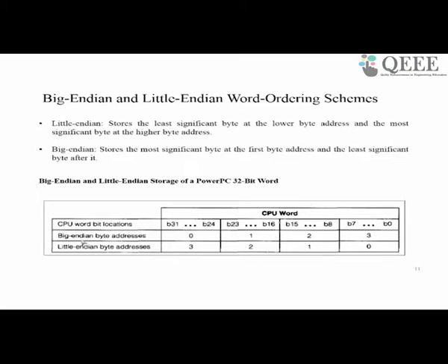Let us say we start storing the bytes at location 2000; then we use locations 2000, 2001, 2002 and 2003 to store the 4 bytes. When the processor reads 32 bits, 4 bytes are read from these 4 locations and transferred in one go. Now we need a convention for how we pack the 4 bytes of the 32-bit data in the 4 different locations.